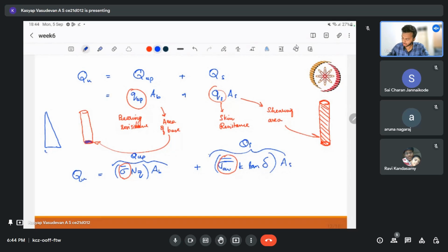So this particular pressure we have to take it here, but this is the average pressure. So if we are idealizing the vertical pressure as in a triangular form, the average will be half of the base. If you take an average of the triangle as an equivalent rectangle, the side will be half, because that is the average stress happening in this curved surface.